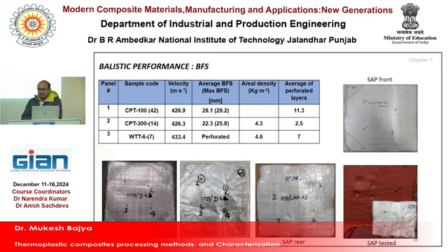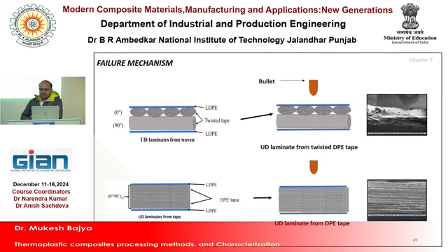We found an interesting result: when we converted this UHMWPE disentangled tape into woven structures, the structure at the same weight failed. But when we prepared the cross ply laminate composite with the 0/90 pattern, with the same material and the same areal density, that is the weight of the panel, we were able to stop the bullet.